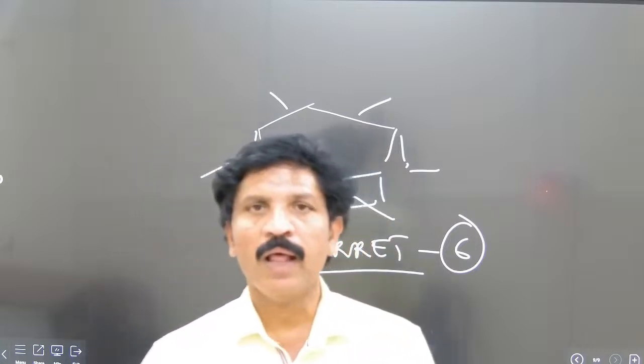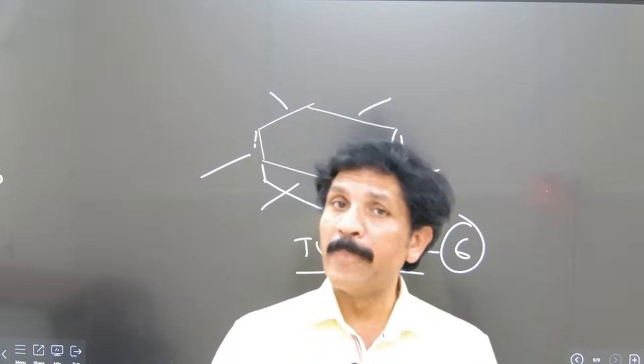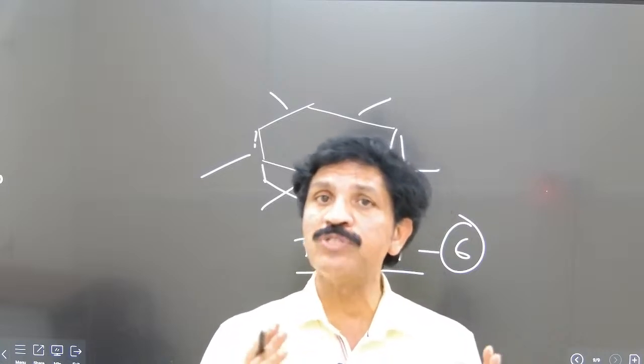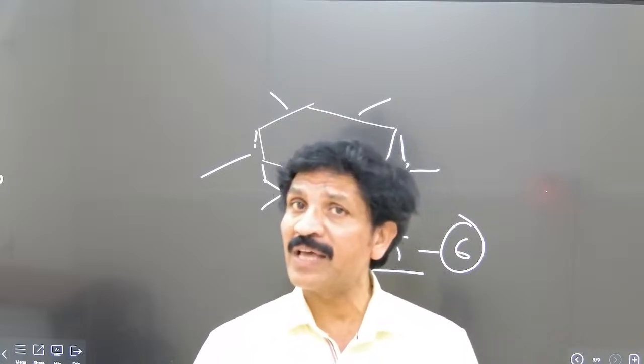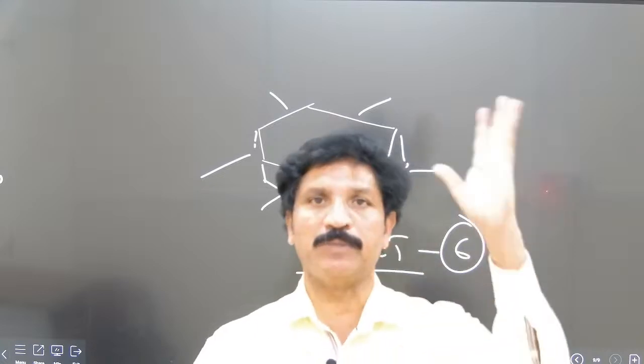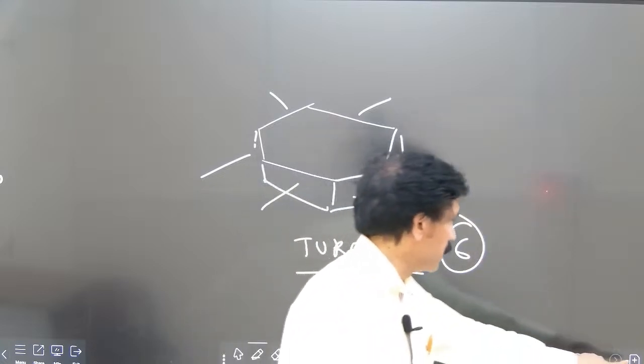And next, what are the materials which are used to manufacture each and every part in the lathe machine. Coming to here, the headstock is totally manufactured with mild steel, because it is the toughest one, the hardest one. The base is manufactured with the casting process, because it has to carry the maximum load.